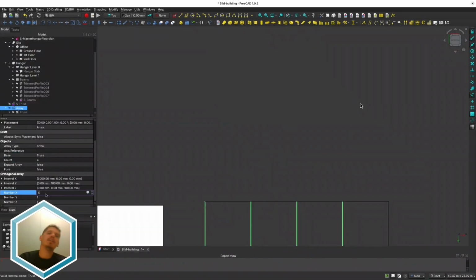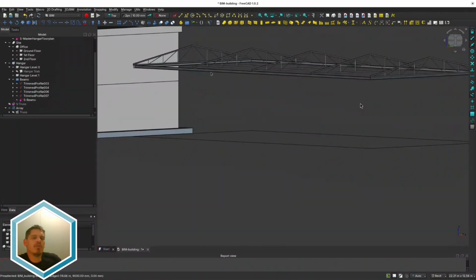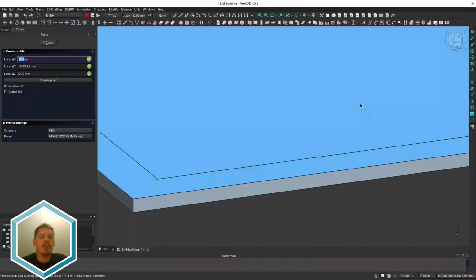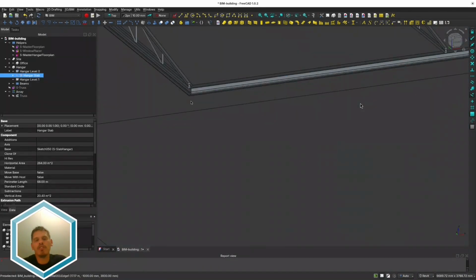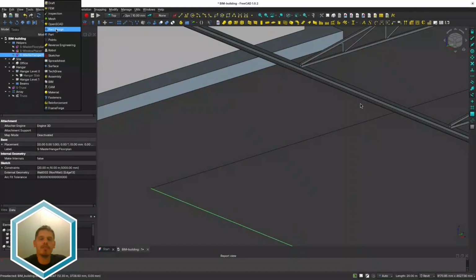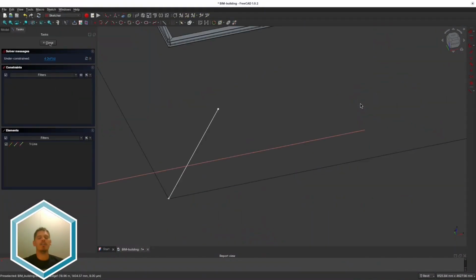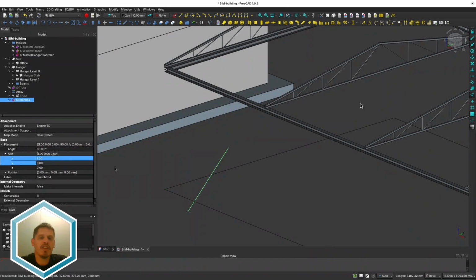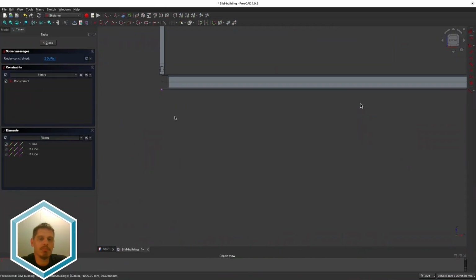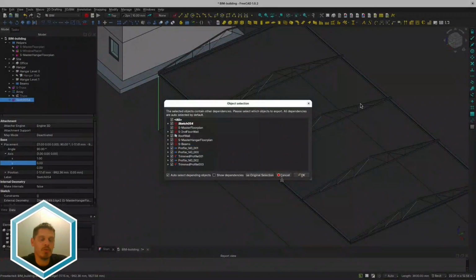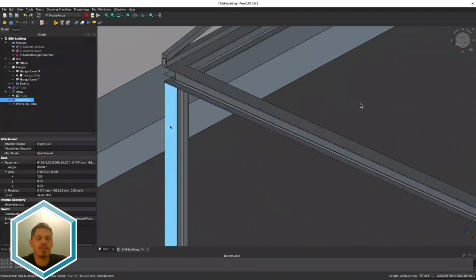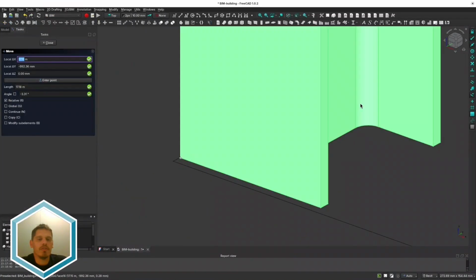Then I use an array, and this is a bit where it gets tricky. I don't know if this is still BIM, if you still get all the smart data, like the trusses independently from the BIM workbench. Yes, they should have all the BIM data, like the material and the weight, all that good stuff. But if you throw it into an array, I don't know if it actually keeps it, going from 1 truss all of a sudden to 5 trusses, if it keeps all the BIM data, or if it duplicates it by 5. We do have 6 pieces I think. Or 5, don't care.